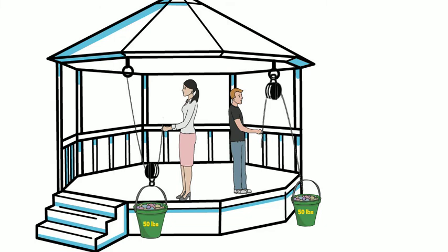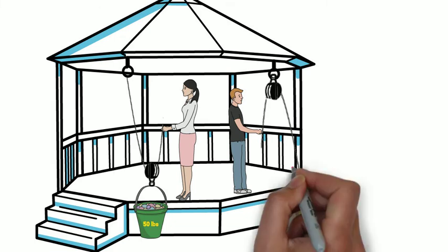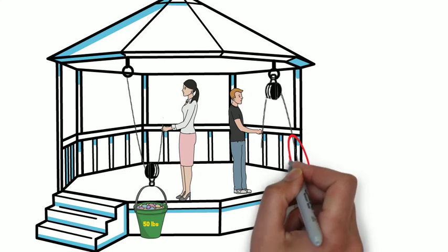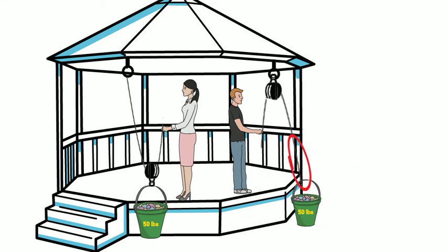But let's look closely at Peter's setup. He has just one rope going to the bucket, as opposed to Sandra's 2 ropes. This makes load sharing impossible. All of the load is going to just one rope. We know from looking at Ron's configuration, and through the idea of load sharing, that Sandra will need to lift just 25 pounds.